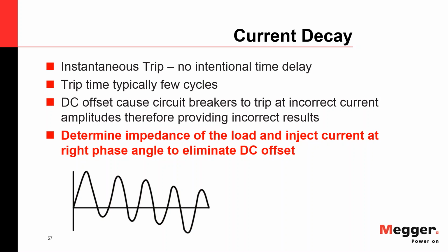So on a classic tester, you have to do 2 injections before you start doing any testing. You have to verify that the numbers are at least very close, and you verify that there is no DC component. If there is a significant difference, then you have to start adjusting your firing angle and do 2 more injections, depending on how close you get. And you have to keep doing that until you find the minimum between the 2 values.